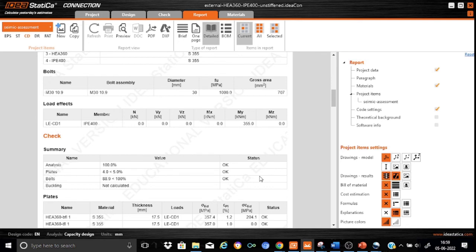And let me just tell you, in this very specific case, we have designed a partial strength joint, and the EC, the European code in its present form, does not have much detailed implementation of partial strength joints. But as specified by the code, the use of such partial strength or semi-rigid connections has to be established by actually performing the inelastic or nonlinear analysis of the structure.